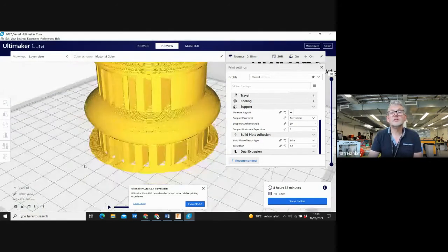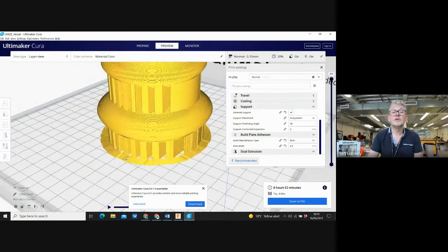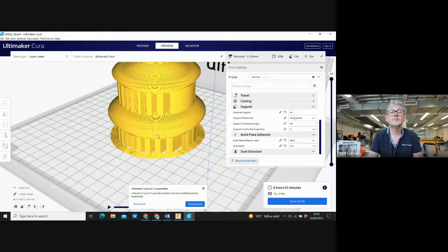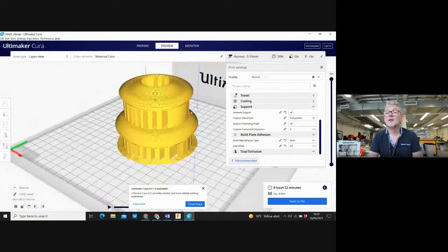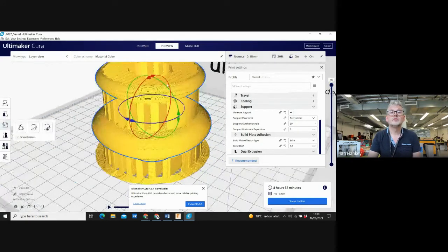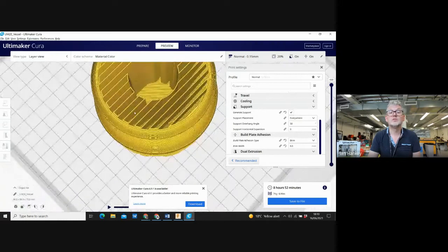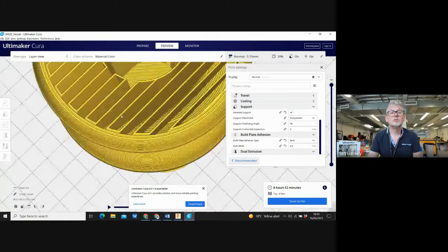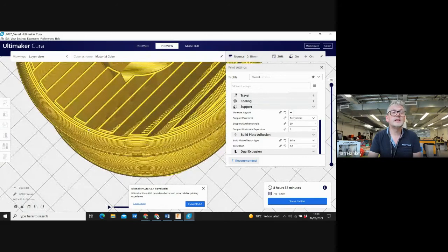And also we can see there are 465 layers, we look right on the right hand side here, 465 layers in our model. I can prove that because it's a sliding scale. I'll just get everything in the screen there. You can grab the top there and left click, and then as you go down, we can see the support material inside. Sorry, I'm just going to move that around so we can see it. But we can also see the outside edge, the inside edge, and a 20% infill between it there.